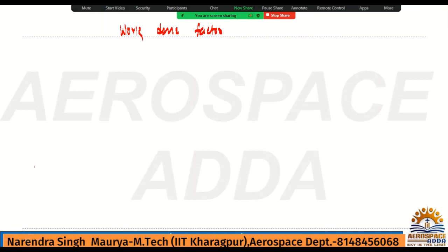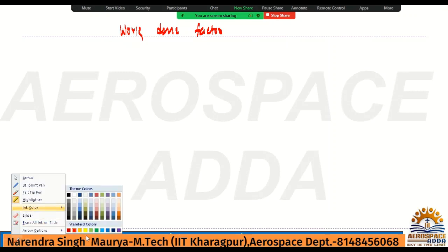Okay, work done factor. So actually, the value of this work done factor at the starting, like the first stage, second stage, will not affect much. But once the number of stages increases, definitely, because it is a compressor, high pressure will be developing, and due to the adverse pressure gradient in the compressor, the boundary layer along the duct, its thickness will be increasing. So I will show the diagrams, you will understand easily. Okay, it's not a difficult thing.